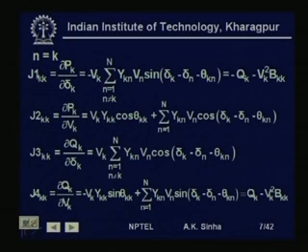So, for the diagonal elements of J1, that is del P_k by del delta_k, we have the relationship del P_k by del delta_k is equal to minus V_k summation n equal to 1 to capital N, where n is not equal to k, of |y_kn| V_n sin(delta_k minus delta_n minus theta_kn). This comes out to be equal to minus Q_k minus V_k squared into b_kk.